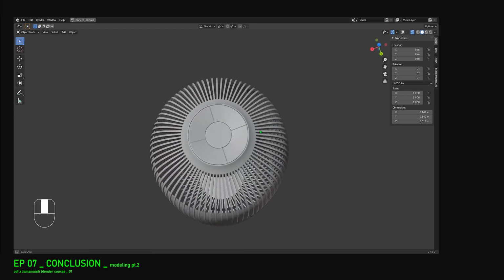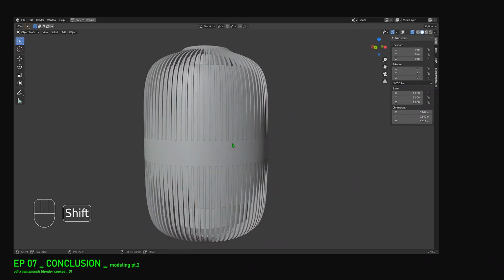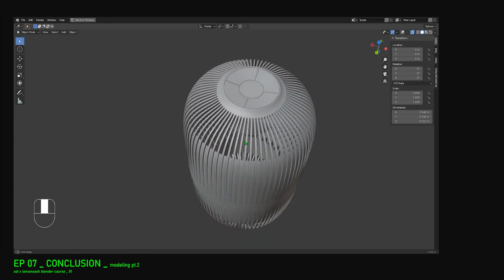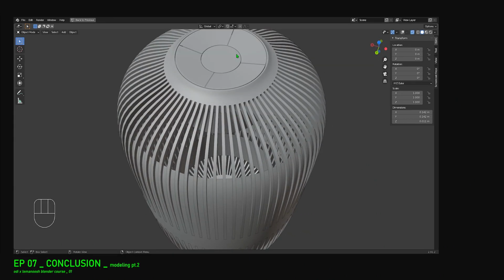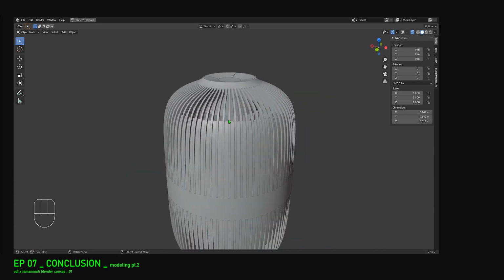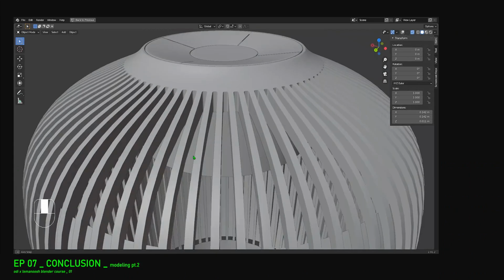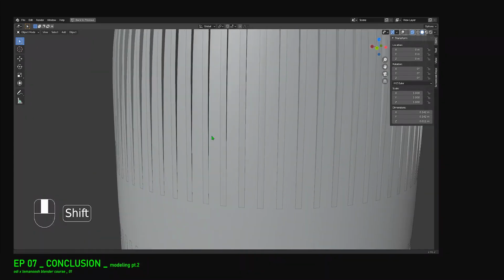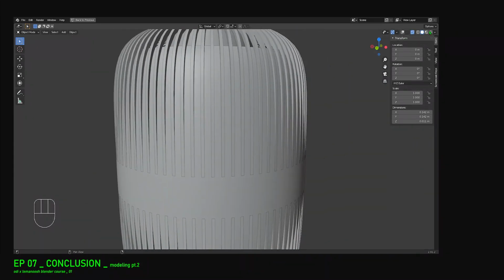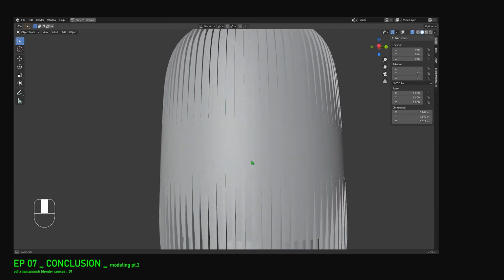And also we saw how to manage a circular array, which is pretty useful in some specific cases. And we also saw some mechanics like how to separate object from one main object, and also the fact that you can just intersect things together and it won't look wrong. We can especially see that if you disable the outline here, you can see that things are blending together.